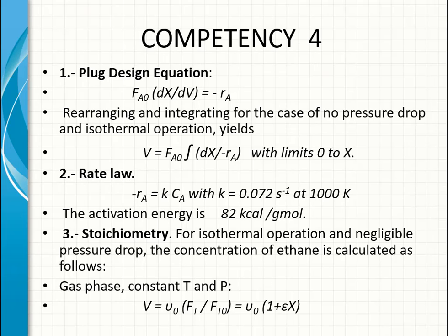Rearranging and integrating for the case of no pressure drop and isothermal operation, T equal constant and P equal constant, we will have that the volume is equal to FA0 times the integral of dX divided by minus rA, with the limits 0 to X. And from the rate law, minus rA is equal to kCA, because they said it was first order, with k equals 0.072 seconds to the minus 1 at 1000 K. The activation energy is 82 kilocalories per mole gram.